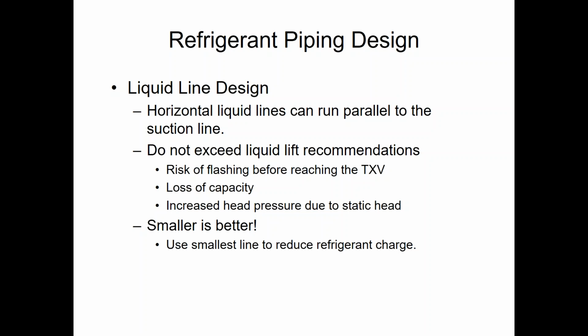So you could have 2 pounds of refrigerant per foot. You go down to little 3/8 pipe, you got 0.6 ounces per foot, and it's all got to be accommodated for. And we want to make sure that if we have long lines or oversized liquid lines, it doesn't equate to more than the 4 pounds per ton number. So those are the risks of oversizing liquid lines.